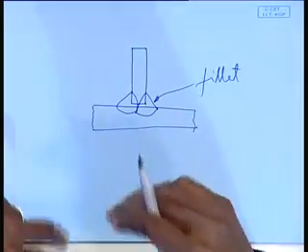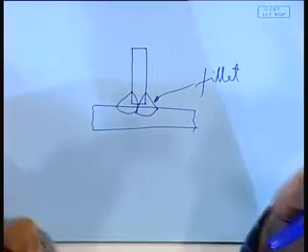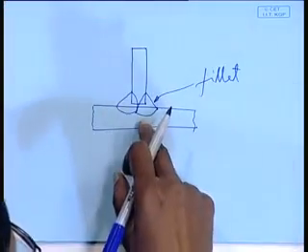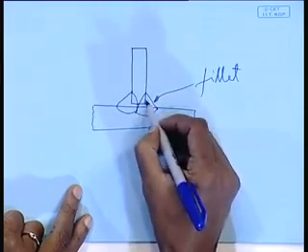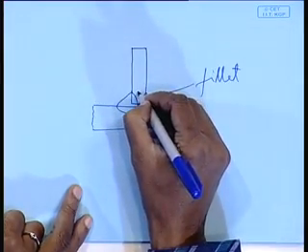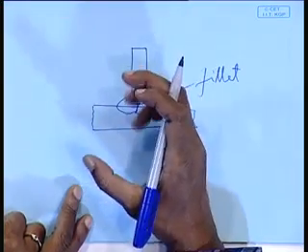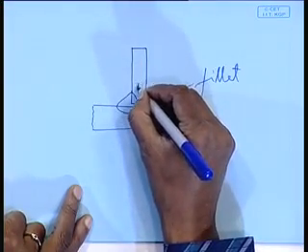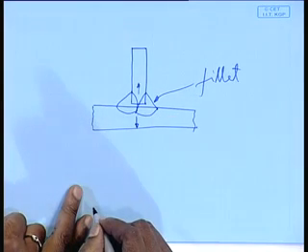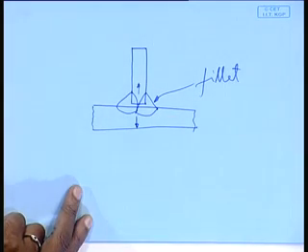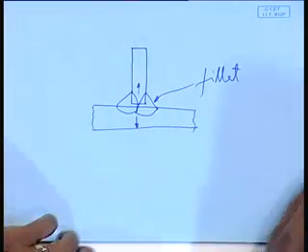Fillet welding, an immense amount of fillet welding, is done in the ship structure; all the stiffened panels are essentially fillet welding. So, when you do fillet welding, what is happening? The material around the weld zone shrinks, isn't it? This part is shrinking in this direction, that part is shrinking in that direction, right? A shrinkage force works, and depending on the situation,